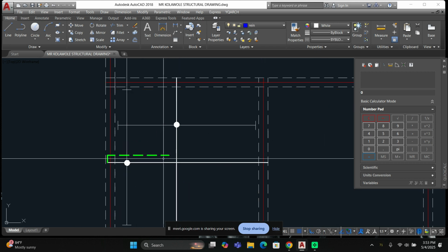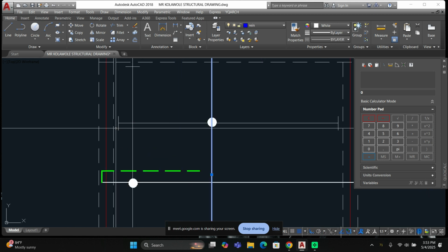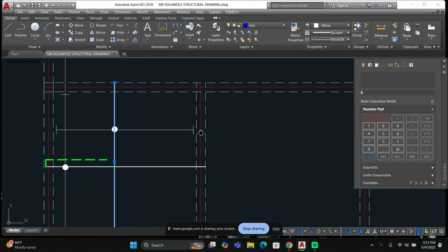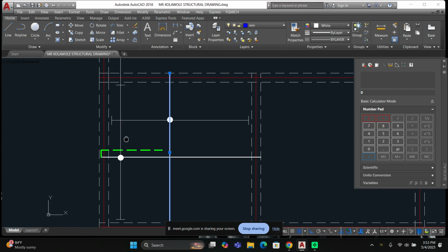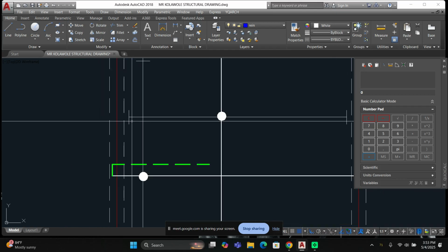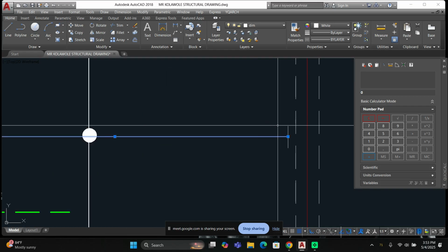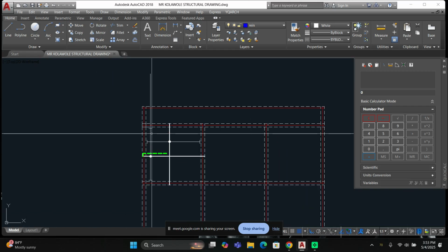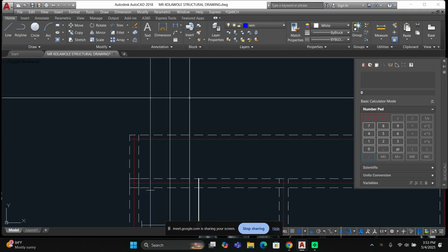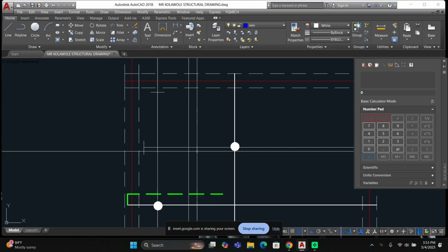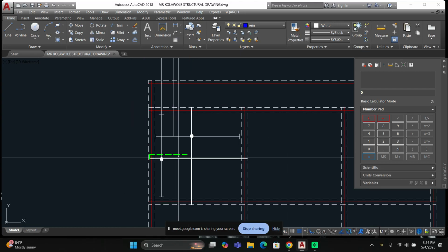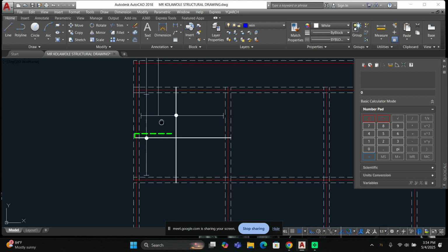Okay. So that means this reinforcement is spanning. They are going to arrange it from this center to this center. Do you understand? They are going to arrange it from this beam to this beam. That's the definition of this. You understand? So now I want to call it out so that they can know how many pieces of reinforcement are going to be there. Maybe Y12, Y16, any diameter of reinforcement. Okay. So calling it out will now be okay.